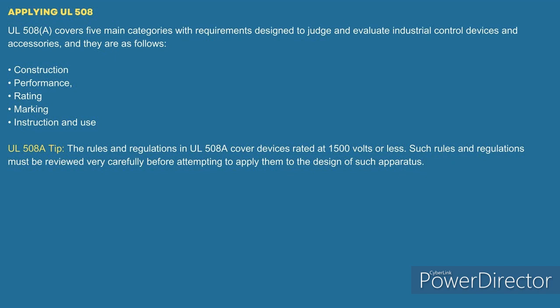Yeah, so it would be 110.26(A), Andrew, and it basically says if the equipment is likely to be worked on while energized. So if that shunt trip is likely to be worked on while energized and it doesn't have working clearance, then you need it. It would. And that's what I was saying. It depends how you look at it.